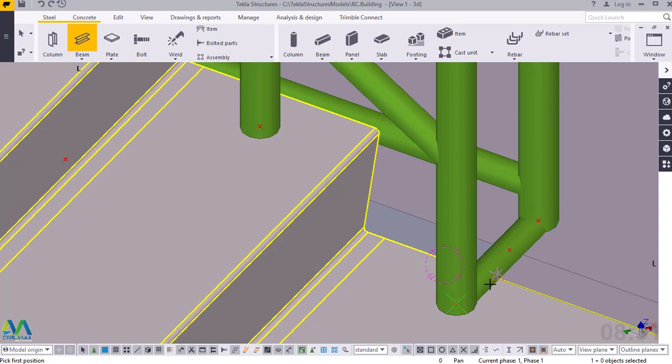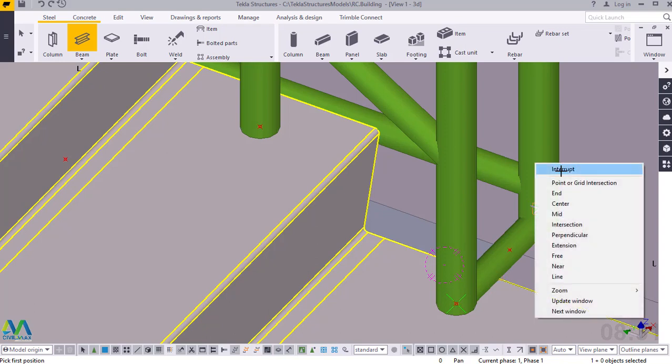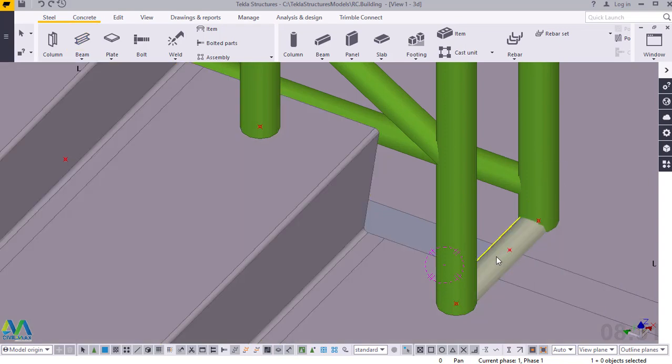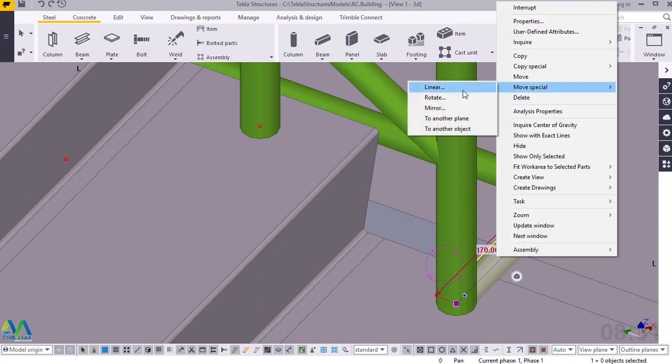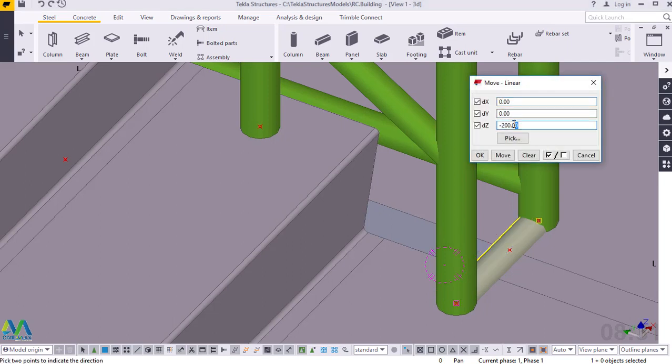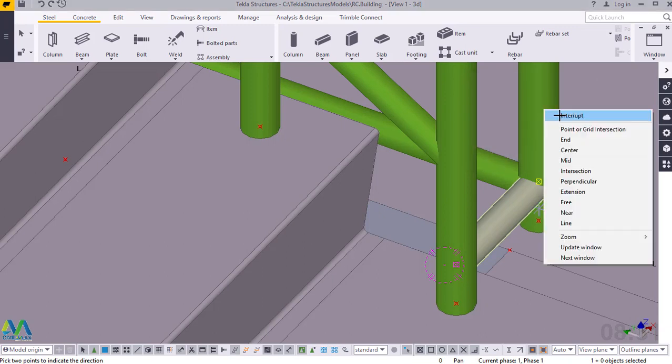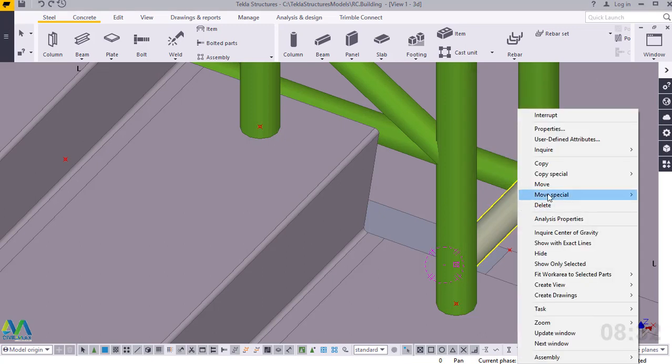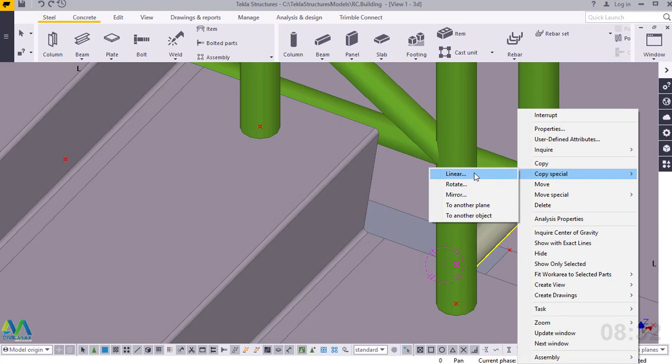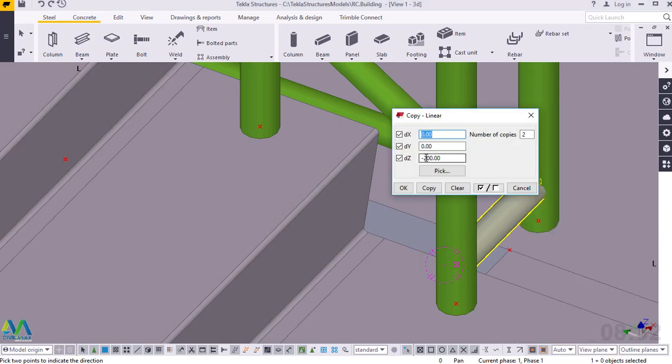That 33.7 times 3mm thick is picked as a default on every creation of steel member. I'll click on that, right click. I want to offset it by 55mm up. Then from here I want to populate this up by 200mm. I'll remove the negative sign prefixing our 200mm and add 3 here. I need 3 of these. Then I'll click copy.